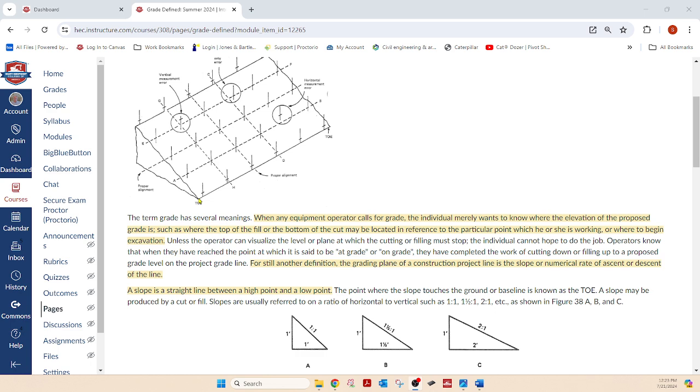It's going to say in some of the problems you come across the width. When they say the width, they're talking about the depth, really, how deep it is. And when you measure, you don't measure the slope from the top down the slope. You got to measure straight out and down. And there's a way to do that, and we'll get into that.